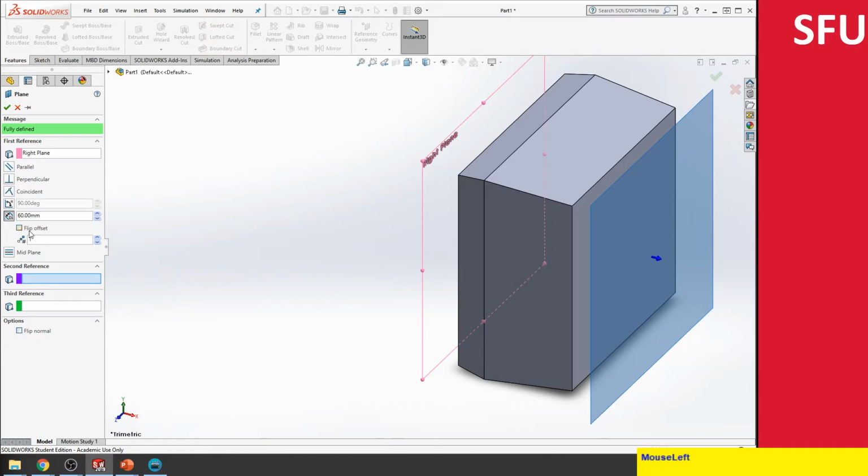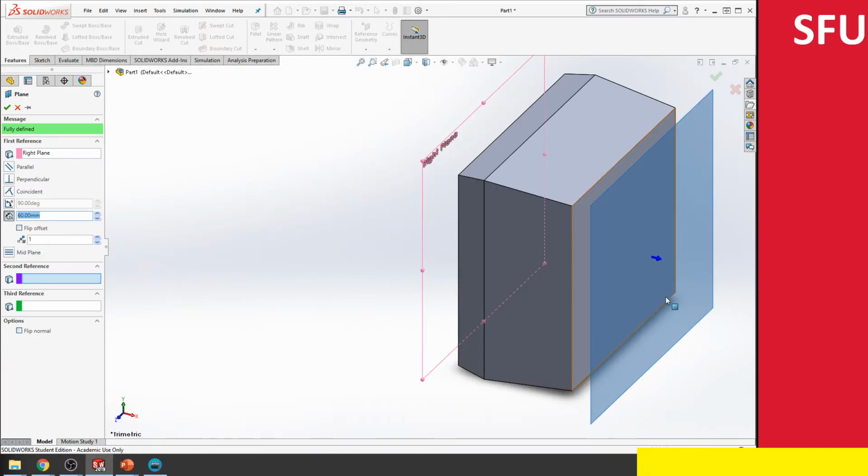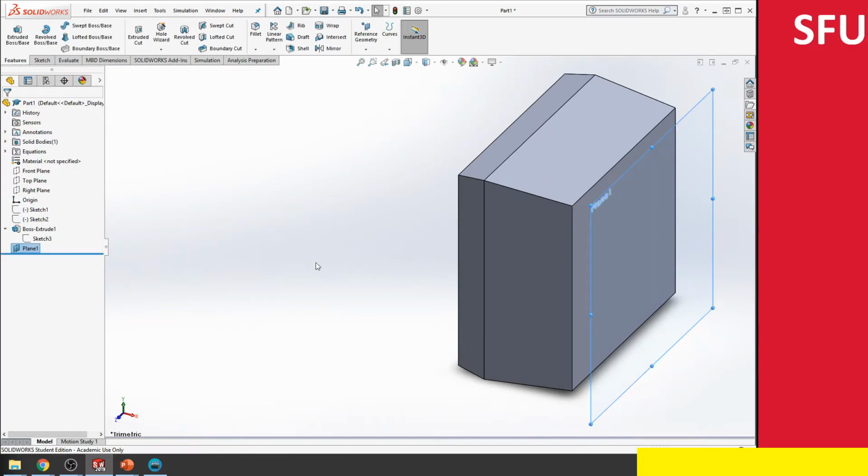I can flip the offset direction so it goes on the other side. Now I go up to here. So we have gone up to 60. You can adjust these values. Because we just have one plane, it's going to be at a particular distance from my right plane. If I had two planes, I could create an angle and do more complicated things. But for this particular case, we're going to leave it as an offset plane and just select OK. Now, this is going to illustrate two parts.